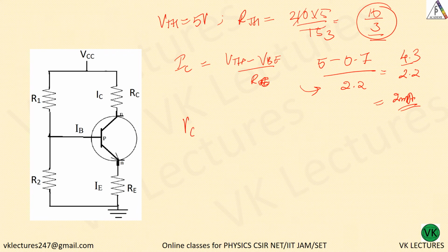Now what is VCE? VCE equal to VCC minus IC into (RC plus RE). What is VCC? 15 volt.